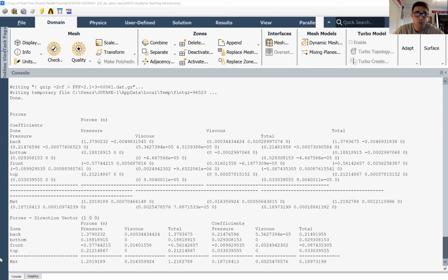And then the last portion of this is the streamlines, which is basically just showing you how the air is actually flowing over this object. So you can see we have this big wake region over here because there's no actual streamlines there. It's kind of just going all around the edges here, which is exactly what we're looking for.